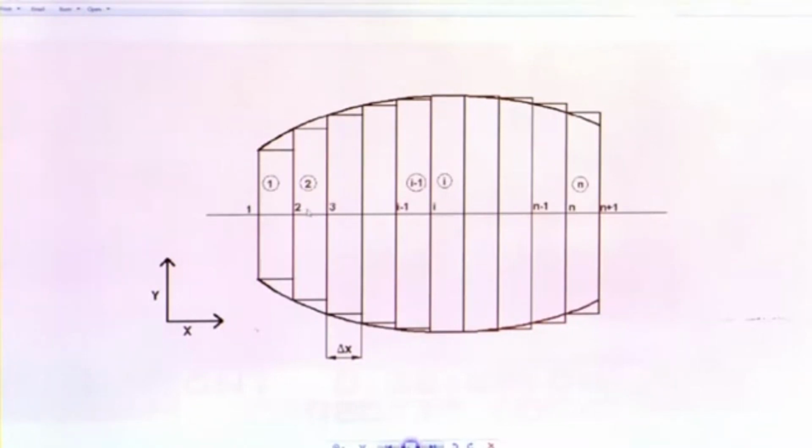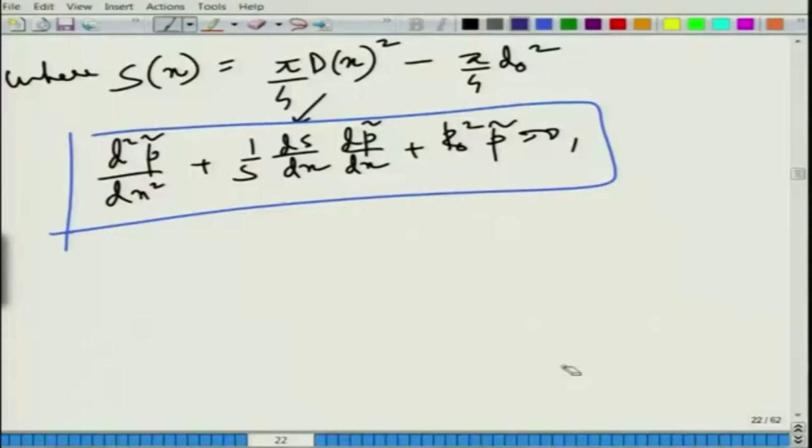So, what happens really at the discontinuity or a sudden area jump, that we have to see. Basically, all these things are a system of small concentric circular ducts or any shaped duct, but with area discontinuity at the interface, that is the key. Such a method, in which we model a gradually varying area flare with short concentric uniform pipes with jump discontinuities at the area interface, is called the segmentation approach.